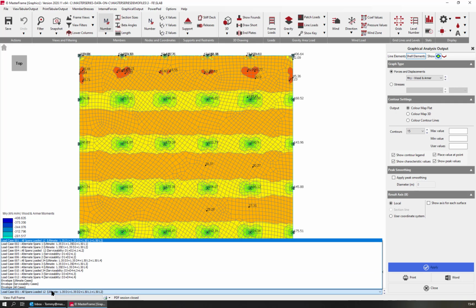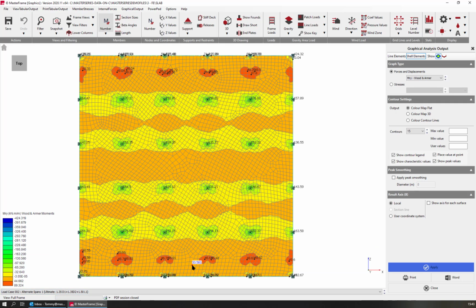Now, if I go to this first alternate, which is max min, you'll see that we get a lot less, of course, but we get a lot more here. The values here are up to 48, whereas previously they were a lot less. So maximum, minimum, maximum-ish. Minimum, maximum's giving us horrendous sagging in the first spans, and that's quite critical. If you remember back to your student days, first span sagging is very high. It won't affect the hogging because that's based on all spans loaded.